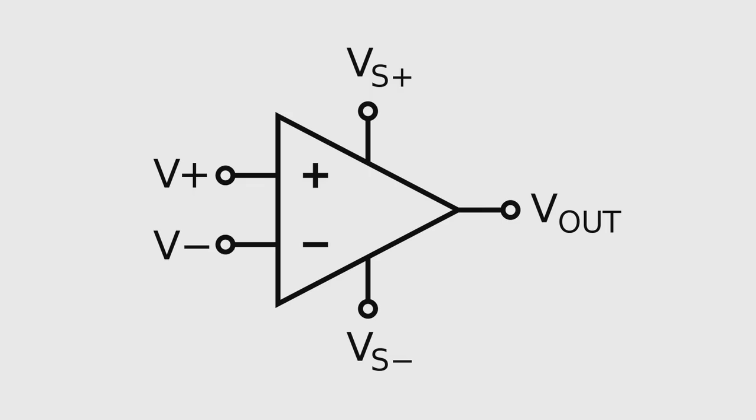And there are many standard op-amps that only cost a few cents. However, some more expensive ones can be up to $100 in small quantities. The amplifier's differential inputs consist of a non-inverting input, plus, as you can see on the top left-hand side, the V plus, and an inverting input, minus. Ideally, the op-amp amplifies only the difference in voltage between those two terminals. That's called the differential input voltage.